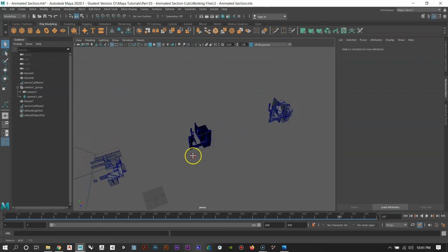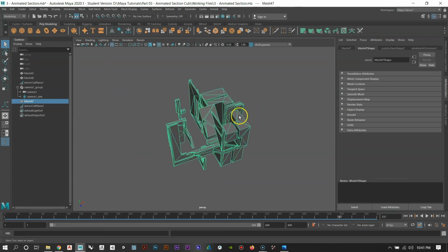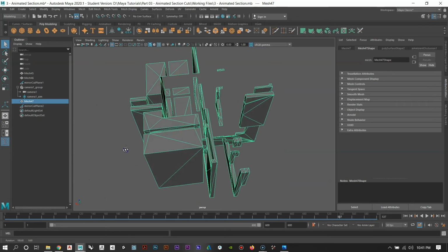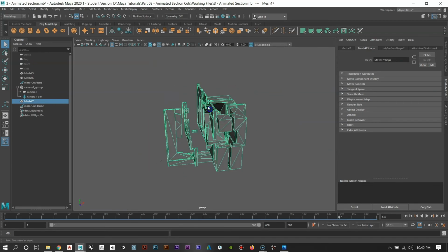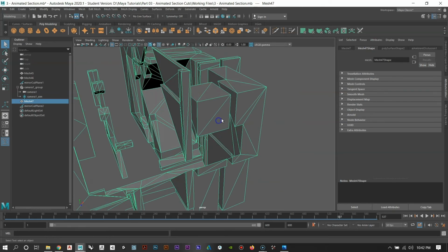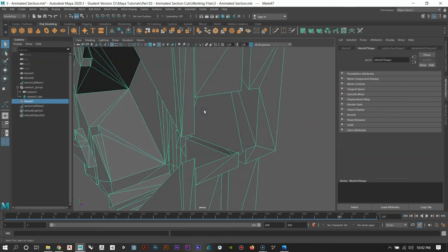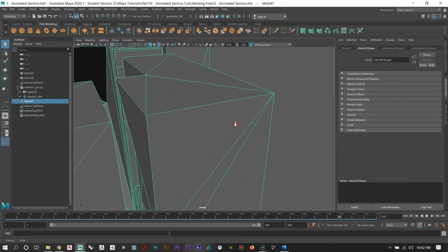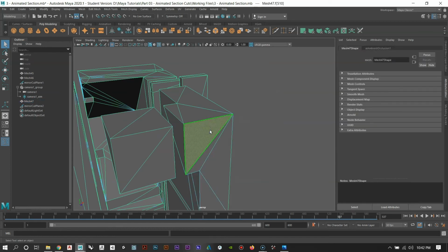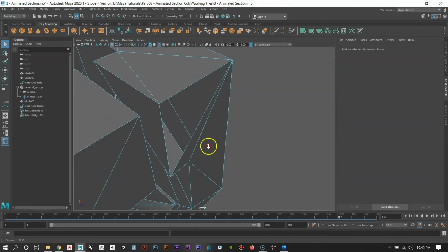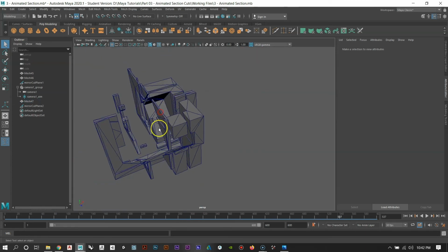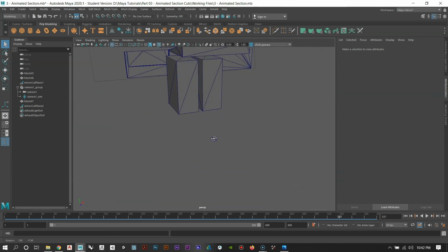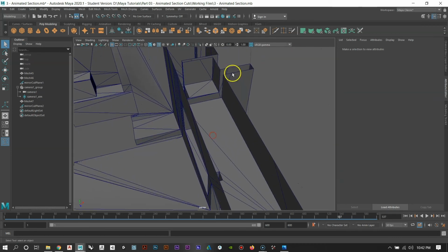And then the third thing that we're going to look at is how to cut through an object with thickness to it. So I've kind of duplicated this object, and right now it has no thickness. Okay, or well, it has thickness, but it has no interior wall quality, right? Meaning if I select a face and I delete that face, there's no thickness in here. Which is why you get section cuts that look like this, right? There's no thickness to this wall.